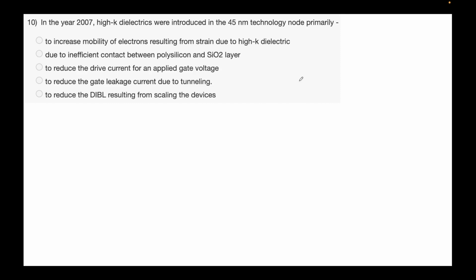Remember that Moore's law said that every 2 years your T-ox can decrease, right? If you decrease that T-ox to a few nanometers, there's something which I told you and which we will be visiting again today, that is tunneling, right? The electrons can simply tunnel through the thin oxide, and once you have tunneling across the gate, this means the gate current is also there. So the oxide is not even an insulator now. So all your analysis, all your science, the physics that you are basing it on, remember, in the ideal MOSFET we had talked about that it's an ideal insulator.